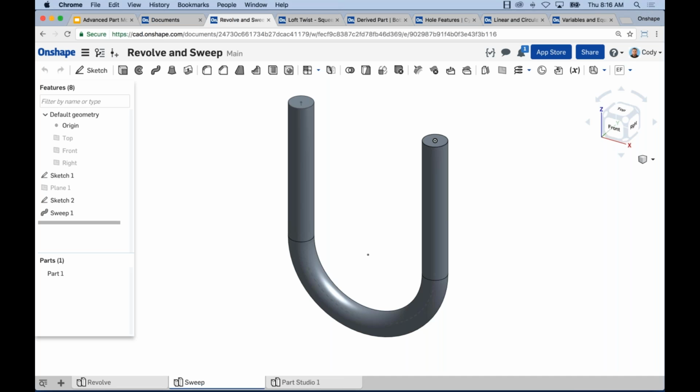Why can't you add standard triangles like equilateral, isosceles, etc. in sketch mode? It's not in any professional 3D CAD that I've seen, but it's, of course, very easy to sketch a triangle using 3 lines. One tip that I would have is if you want an equilateral triangle, sketch 3 lines that join each other in a triangle, and then window select them and set them all to equal. And that's an equilateral triangle. But of course, you can always just sketch lines. There's no specific triangle command.